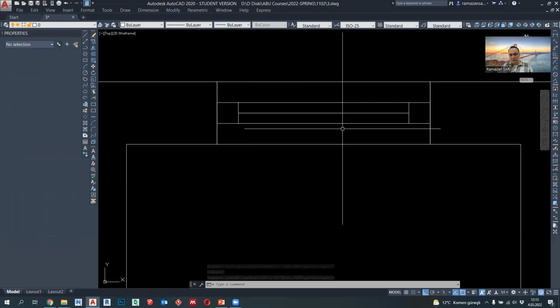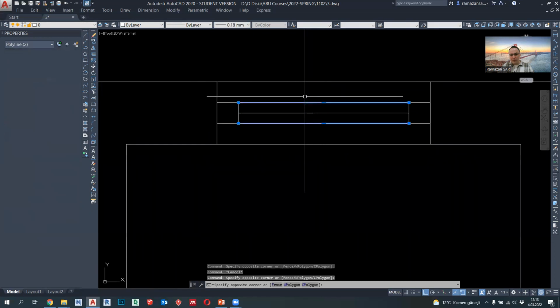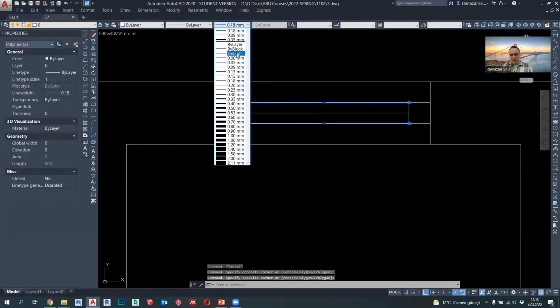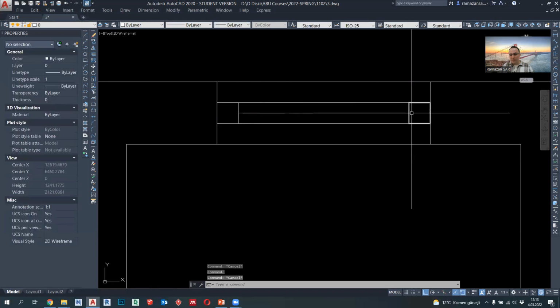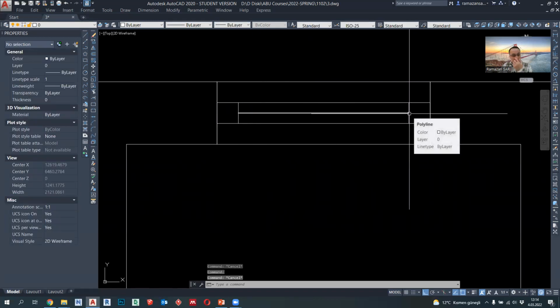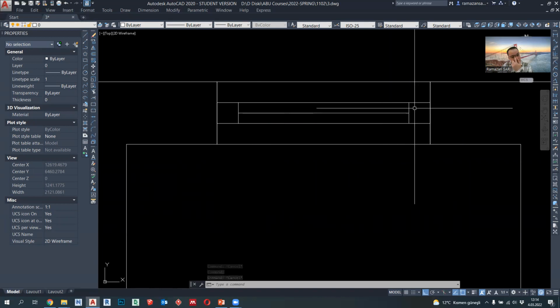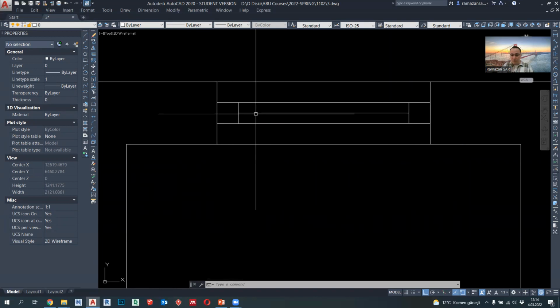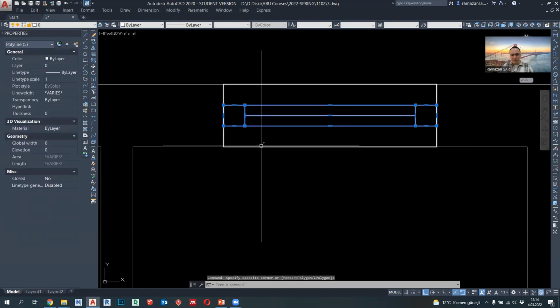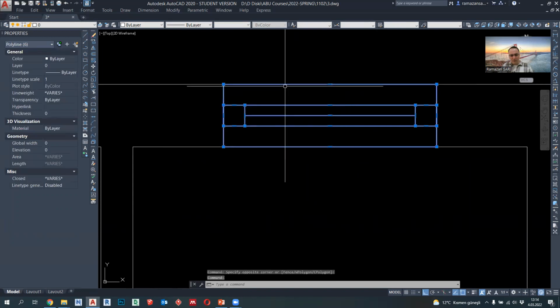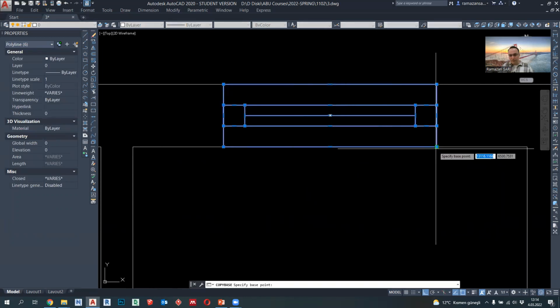Don't forget. Actually, the line thicknesses of this remaining part must be thin line again, while this line must be medium. Why? Because we only cut the frame around the window and the glass. This part is the visible part of the window. That's why. And let's make this setting again block.